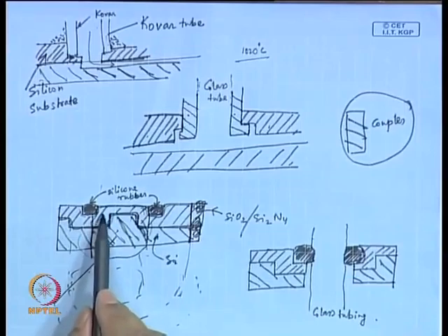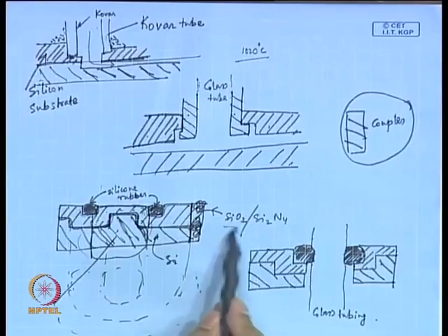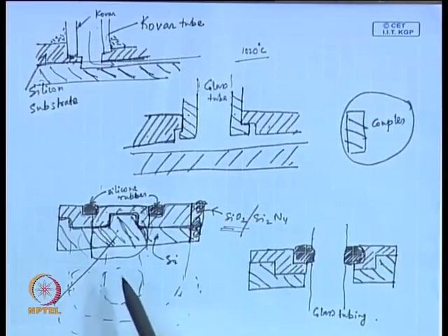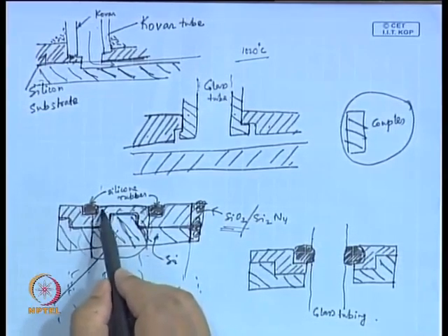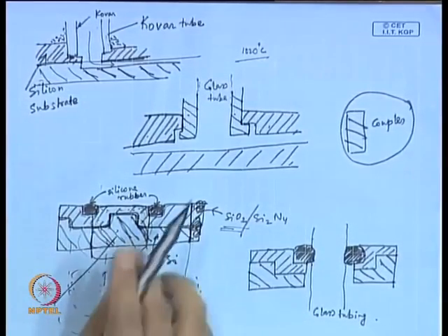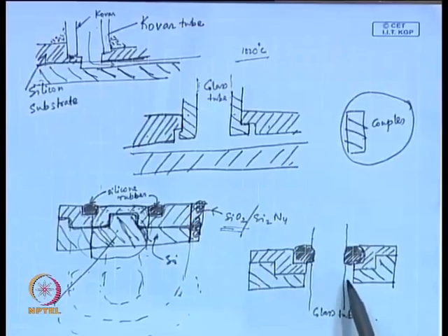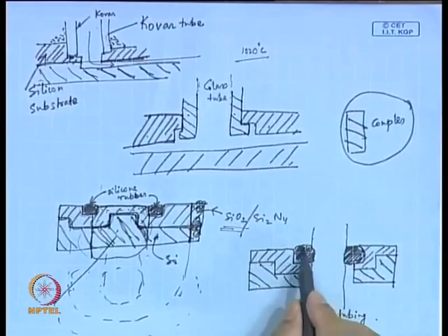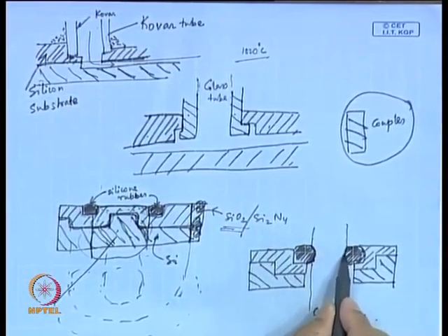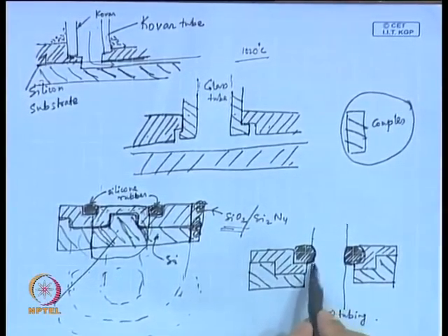And then when you try to etch this layer, it would be difficult. This we pointed out, because SiO2 acts as a mask, it is much more difficult to etch the SiO2 layer. So, for this you have to bring in the plasma. So, you get this part also etched out. So, once you take this whole layer out, what you end up with is a structure something similar to this, where the glass tubing runs like this, and this silicone rubber that you put there is acting as the seal, you see.